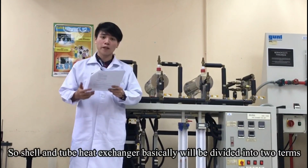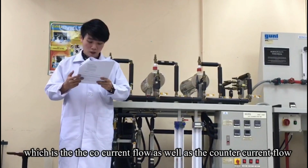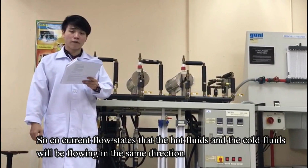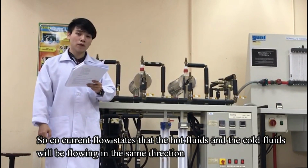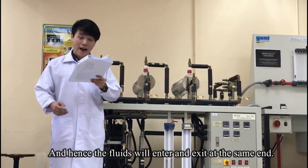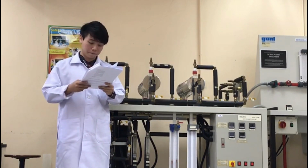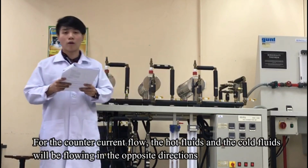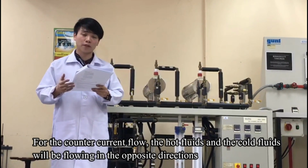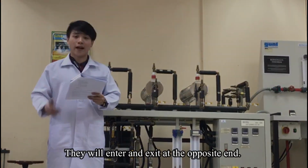The shell and tube heat exchanger basically will be divided into two terms, which are the co-current flow as well as the counter-current flow. Co-current flow means that the hot fluid and the cold fluid will be flowing in the same direction, and hence the fluids will enter and exit at the same end. For the counter-current flow, the hot fluid and the cold fluid will be flowing in opposite directions. They will enter and exit at opposite ends.